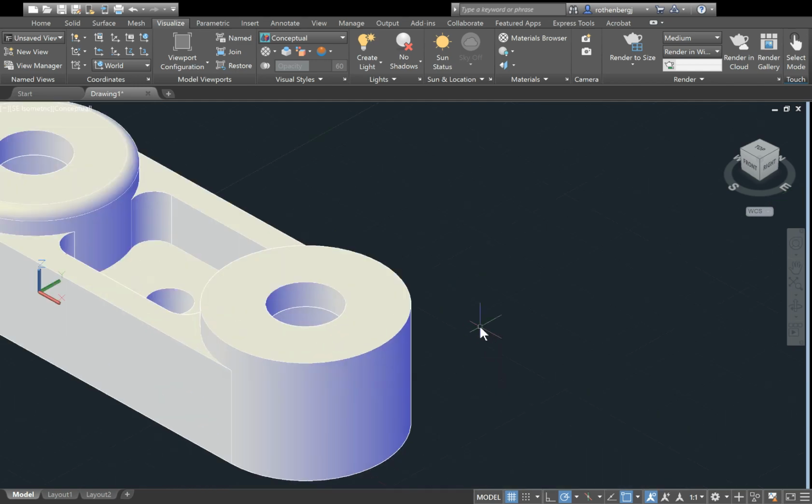So now we will be using the fillet command once more. Once again, select the edge of the cylinder. The radius should already be 1/8, 0.125, but if it's not, change it. Hit enter again, and that's good.